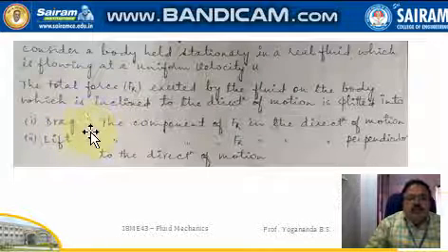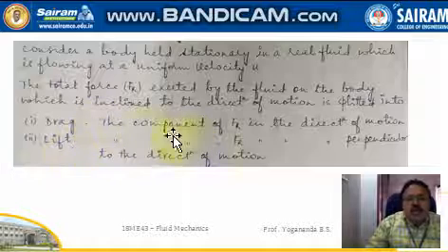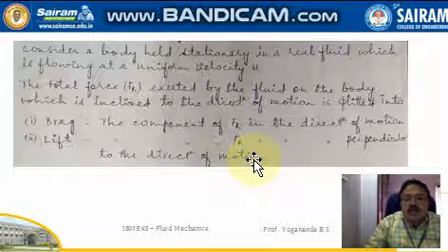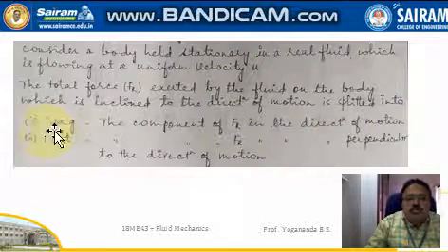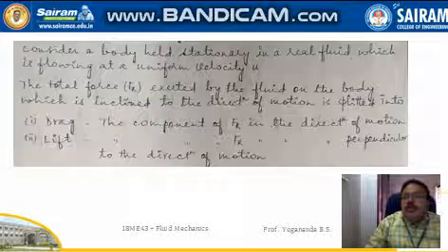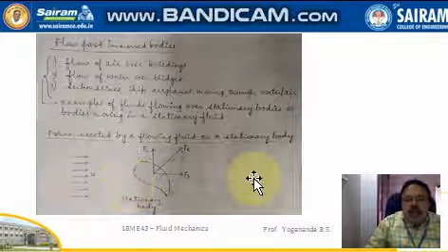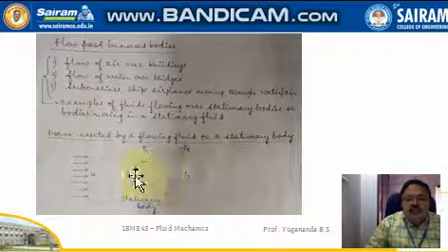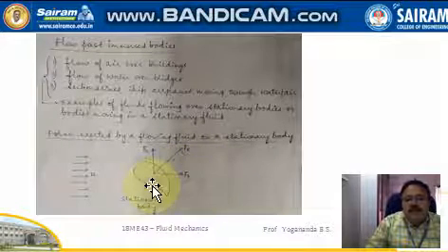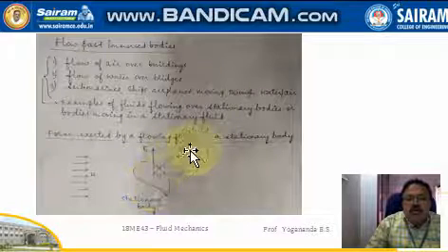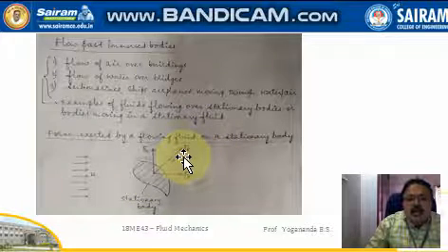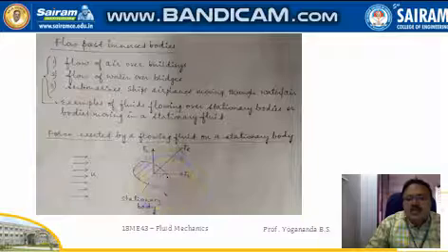When you are asked to write the definitions of drag and lift, the definitions are like this. Drag is the component of this resultant force Fr in the direction of motion. The irregular shaped body shown here will be dragged in the direction in which this drag force is acting. FD is the horizontal component of the resultant force Fr, which is taken as the inclined force to the surface of the body.